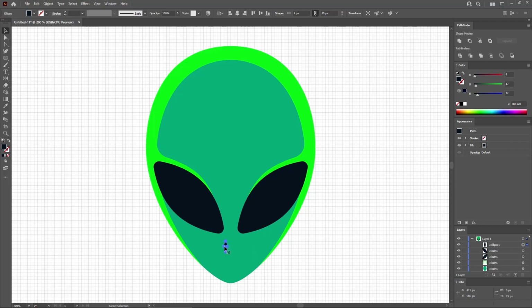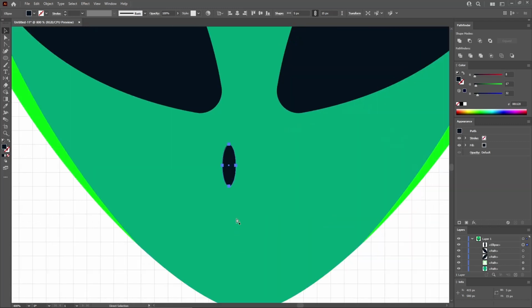You can now press Ctrl M plus several times to zoom in on it. Switch to the anchor point tool and use it to drag the handles of this top point like this. Return to the selection tool, hold down the Alt key and drag a copy of this shape 15 pixels to the right in this position.